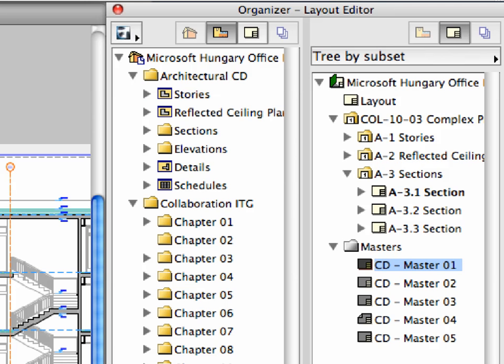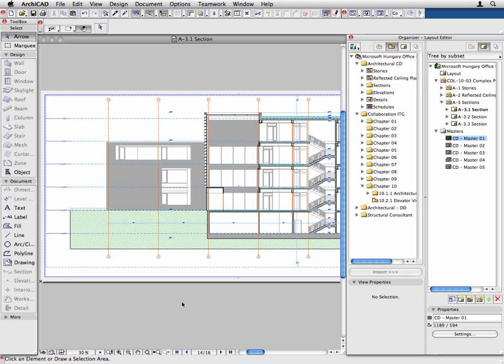The newly created layout sheets are based on the previously defined section layout. You can duplicate the longitudinal section and then divide it into two parts and place it on two separate layouts as we demonstrated earlier in this training step. You can define the names and the layout numbering of the sheets if you wish.